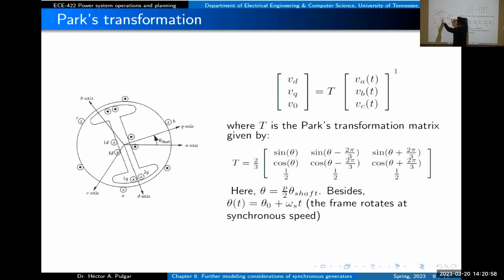I thought you were talking about the rotor, not the A phase. No, we're not there yet. So if the current at some point becomes zero, how much is the flux that you have in that winding? Zero. If the current is maximum but negative, well, same flux but pointing in that direction, right? And the same thing will happen in phase B and C. The only difference is that these are shifted 120 degrees in this graphical description.